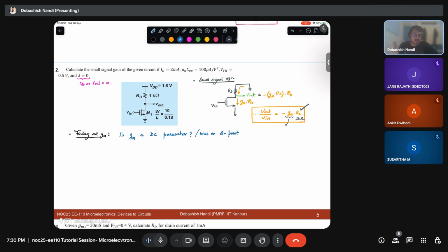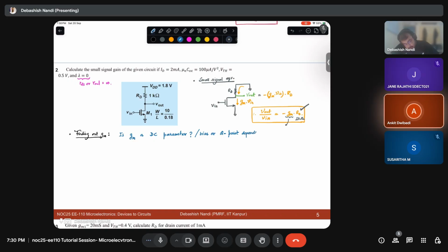Formula maths, we know that it will be dependent on that, but try to interpret that formula in the plotting sense, in some kind of ID-VDS or input characteristics, and then answer. So, sir, in the ID-VGS characteristics, if we plot it, we get a non-linear curve basically. So at different points of that, we get different GM.